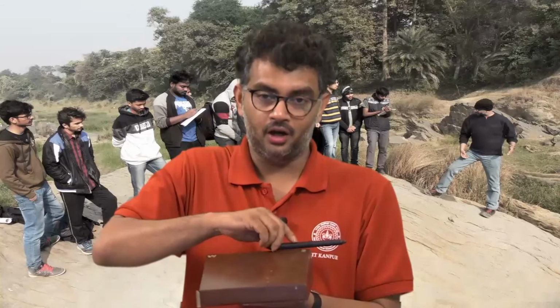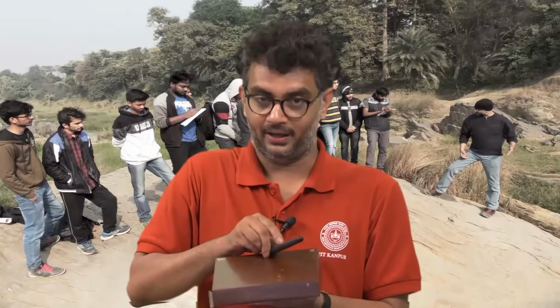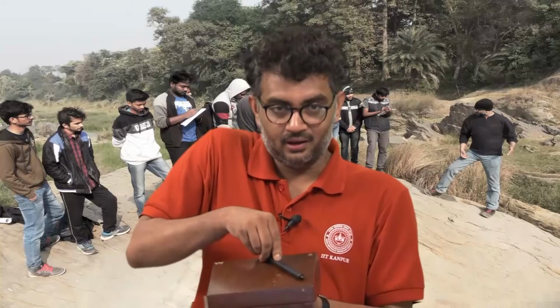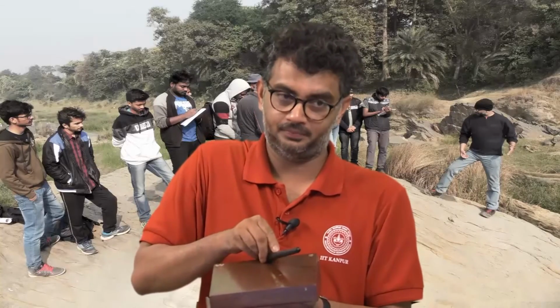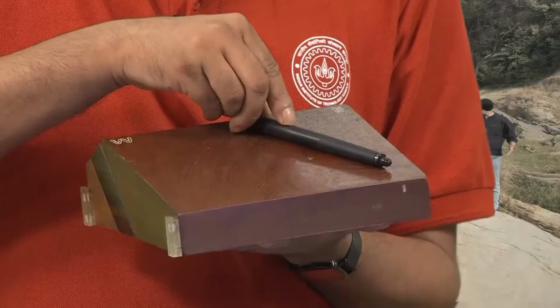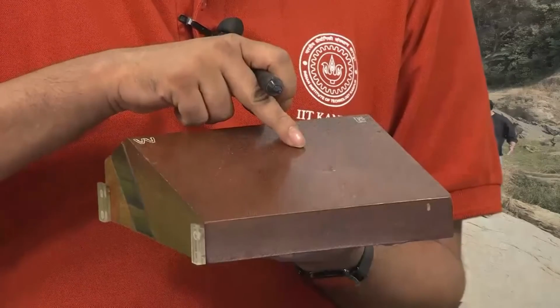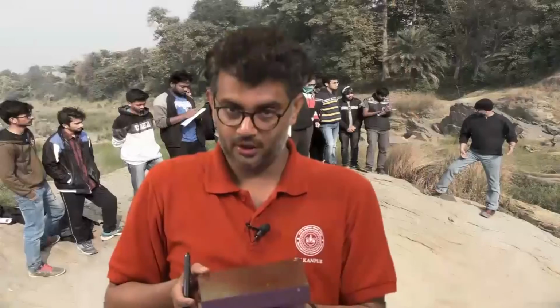Now, if this is my north, then the angle it makes along the horizontal plane, this is my trend. The plunge is the angle I have to rotate this line to project it on the horizontal plane, and the pitch is, if this is the line, then if I measure it on the plane, the angle is the pitch or rake. So, if I try to define it in words, it goes like this: trend is the direction or